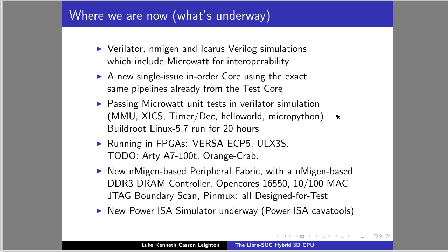Now, I then used that to add the Libre-SOC core to it, so that instead of doing just Wishbone reads and writes directly to the memory locations in order to initialize the DRAM and do the read and write tests, I actually ran the Microwatt cold boot memory initialization sequence as a Power ISA program emulated by Icarus Verilog. And I'm in the middle of sorting that out at the moment.